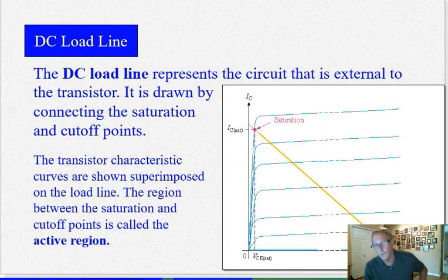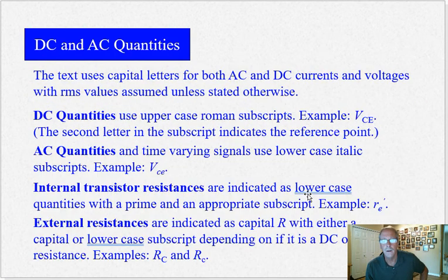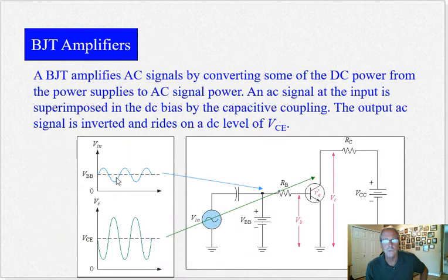More on, more off, more on, more off, okay? And as a result, you get this fluctuation in collector current, up and down, all right? And obviously corresponding fluctuation in the collector emitter voltage. And that's essentially how an amplifier works. So you get this small fluctuation in base current, resulting in a large fluctuation in collector current and a large corresponding fluctuation in collector emitter voltage.